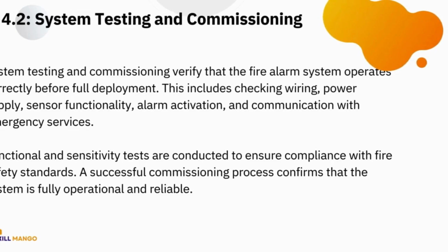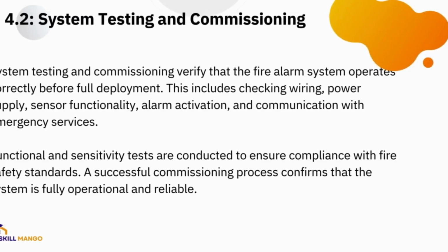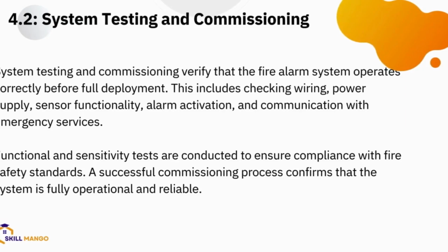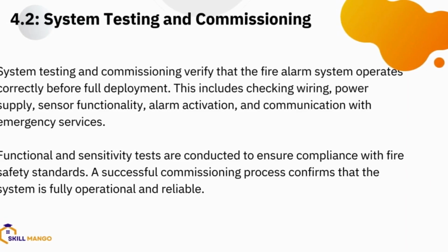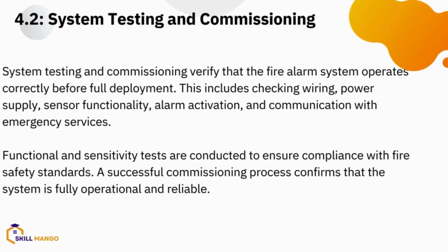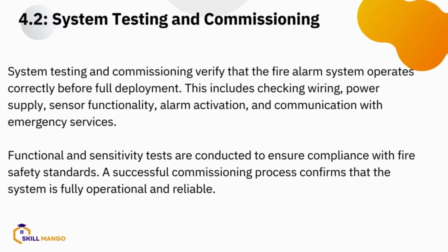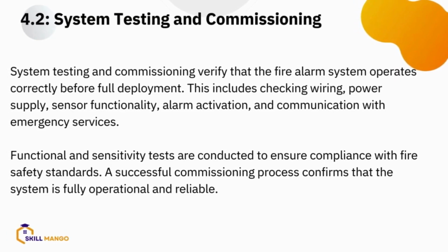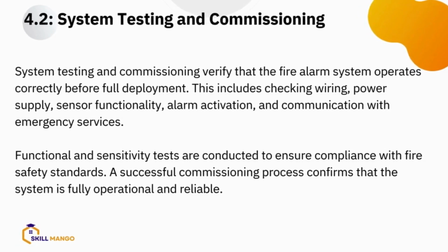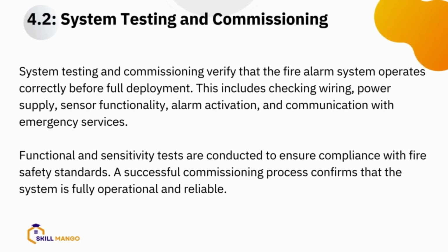Okay, so to test your fire alarm panel, you need to press the designated button. There's a button on the panel, they call it the test button. The button will activate all the connected smoke detectors and alarms in the building that link to that particular panel. This will allow you to verify if they are sounding properly, because this is very important. You have to ensure that they're sounding properly.